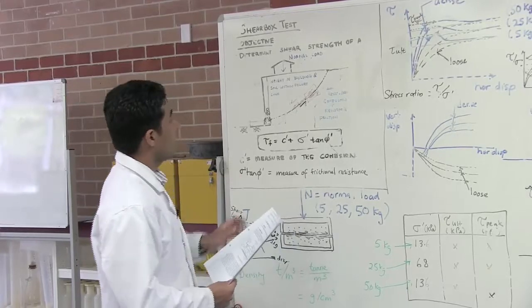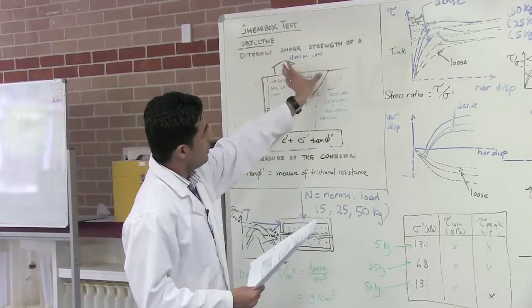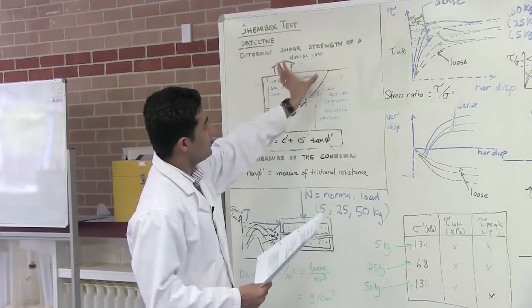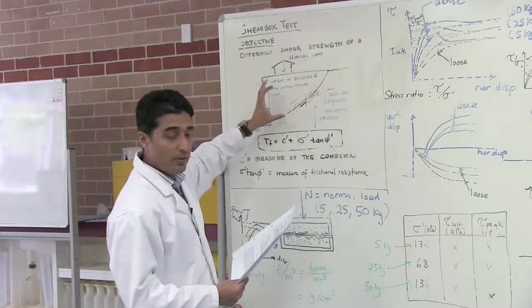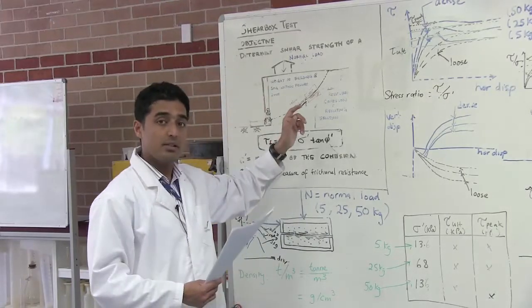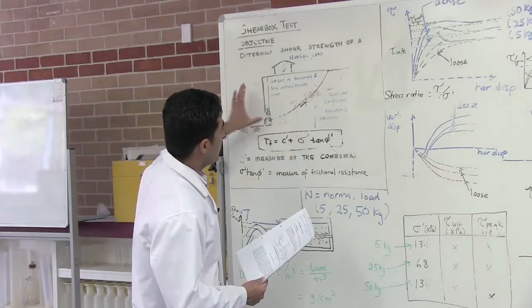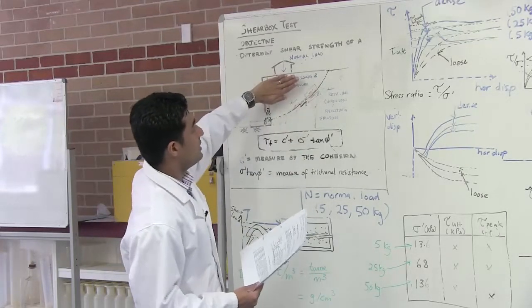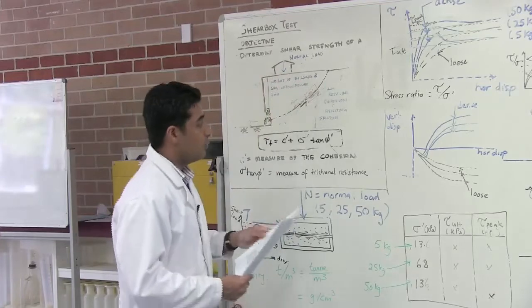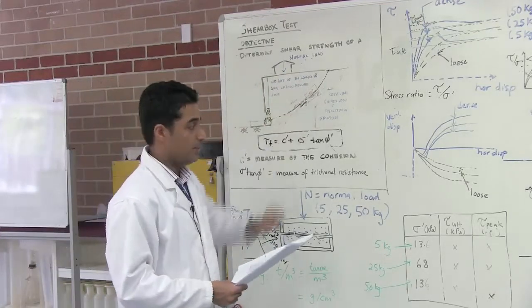sample given. When you construct something on a built-up area like that, this portion of the sand or the soil can fail, and the shear strength of the particular soil sample or the sand sample will have a resistance built up which keeps this wedge of soil here. So our objective is to find out what that shear strength is.